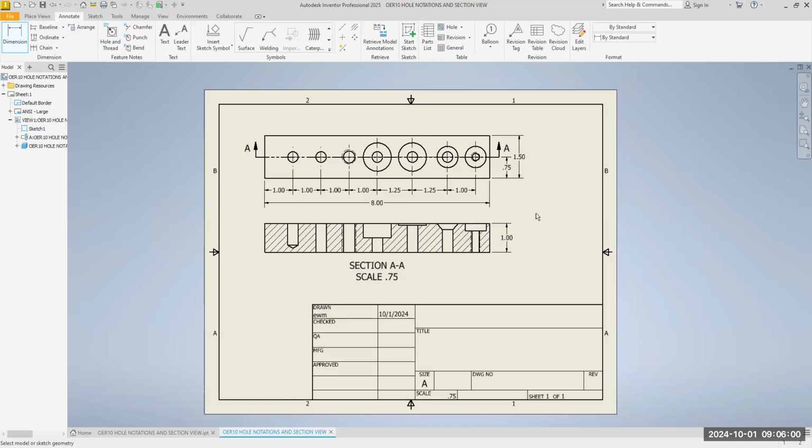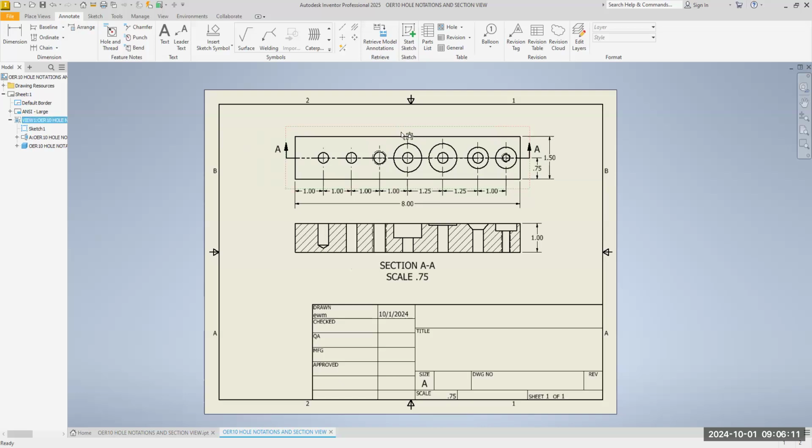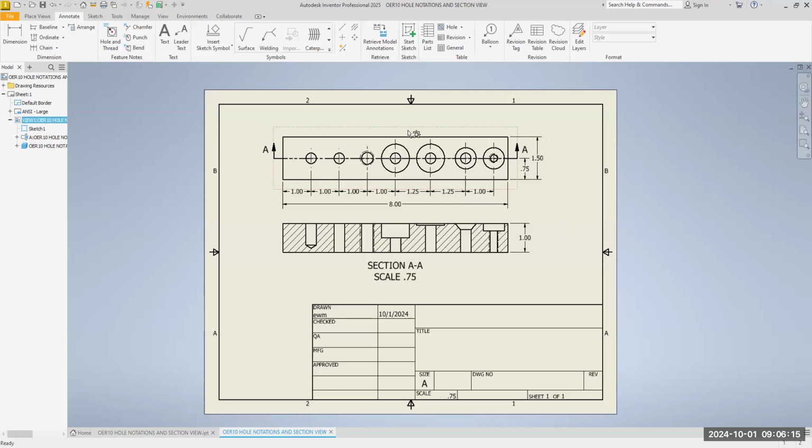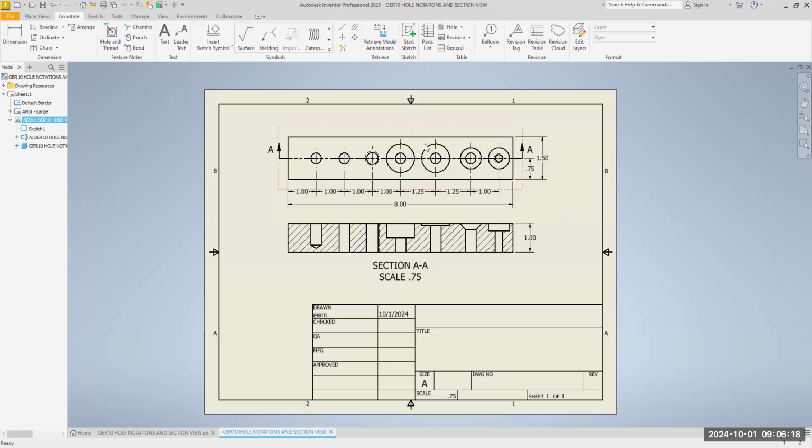Now if you want to center this more, center directly in the page, you can right click, okay. Now watch. If I move my parent view, this is the beauty of it. Look, it moves it over. You might want to center that directly on your paper. Mr. Morris keeps missing the mark a little bit. All right. So far, so good.